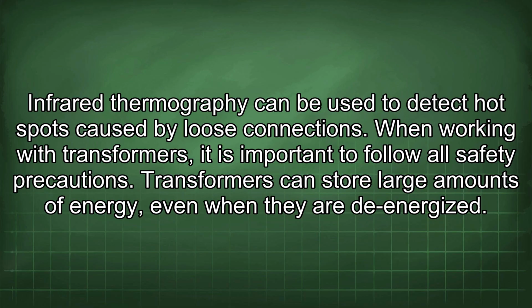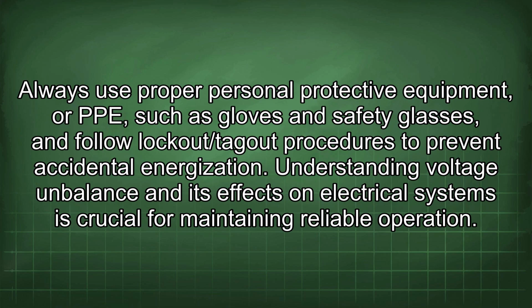When working with transformers, it is important to follow all safety precautions. Transformers can store large amounts of energy, even when they are de-energized. Always use proper personal protective equipment, or PPE, such as gloves and safety glasses, and follow lockout/tagout procedures to prevent accidental energization. Understanding voltage imbalance and its effects on electrical systems is crucial for maintaining reliable operation.